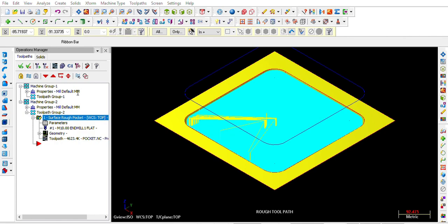If you are having your datum coordinates or datum workpiece coordinates in G54, you can mention it definitely here, or else you can have any other number, G55 or G56 up to G59. You can have any G code position here. So this is the total length of the program. You can see here, 5054 blocks of program have been generated using this software.